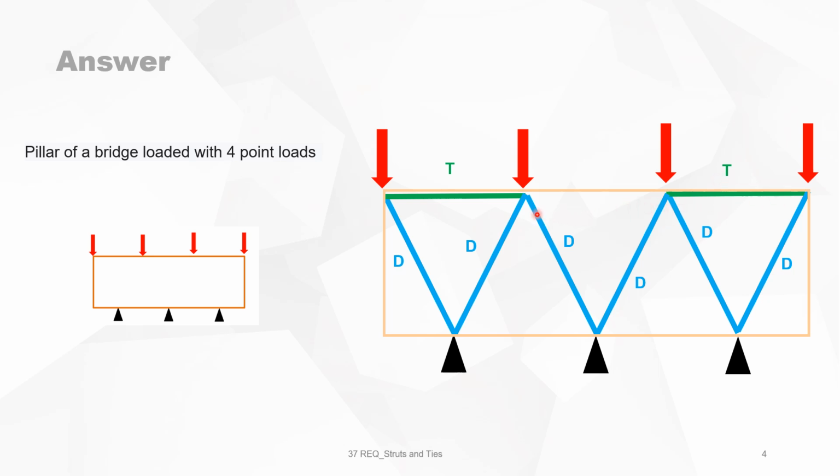And normally on this side, you will have 2 compression struts which are moving away, or it appears so. In reality, it's not, because this support is supported by 2 compression struts on both sides, so they will shorten this bar in the middle. So this is also a compression bar. On the bottom, we have divergence again of the compression struts, so this is tension, and there it's also tension.